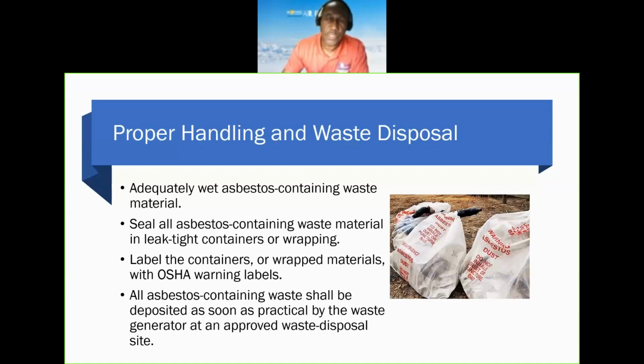Okay, and we can also see proper handling and waste disposal of asbestos. As you may know or may not know, you can't just dump asbestos anywhere or throw it in any field or waste disposal site. It has to be properly bagged and labeled, contained properly, transported properly. As you can see in the picture there, those are properly bagged.